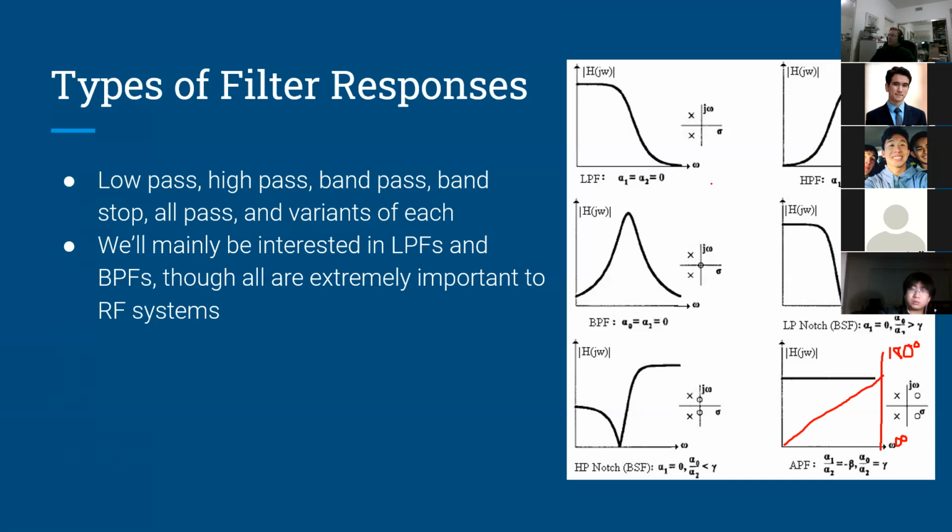So I think one important thing to note here is next to each of these responses is a little diagram. And these are basically plotting the poles and zeros of the filter response. So for the low-pass filter, in this case, it's a second-order low-pass filter. There's 2 poles. And what that means is a pole essentially props up the filter response, the frequency response.